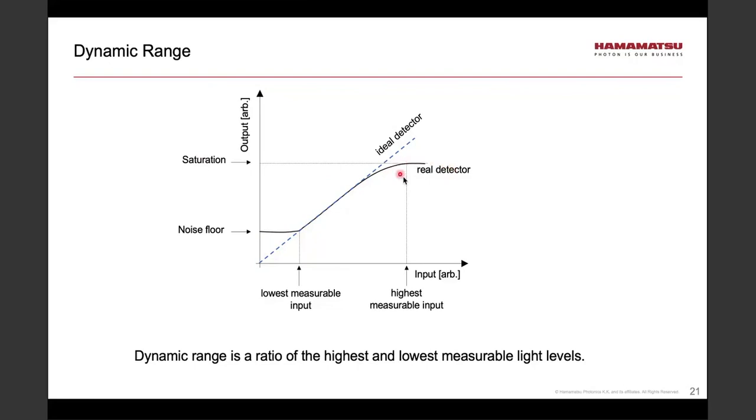This state is known as saturation. Some photodetectors are easy to saturate, like SiPM and PMT, and others are much harder to saturate, like photodiode, but they all saturate at a certain level. Therefore, by dynamic range, I could mean the range of the measurable input light powers. By measurable, I mean a measurement which will yield a signal to noise ratio greater than 1.